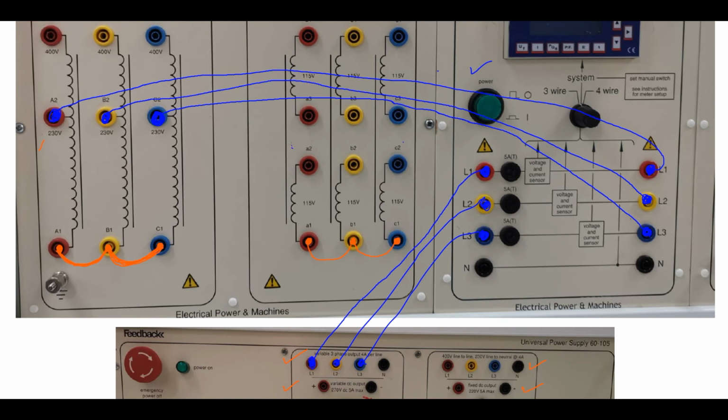Okay, as I told you, we're going to keep the terminals here of the secondary part open, so no connections to be done there. So those are the three connections. The first one for Y and Y connection. The second connection is to connect our supply to our watt meter, and from the watt meter to our transformer.